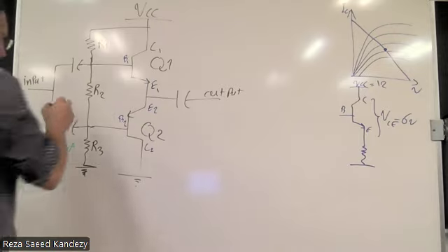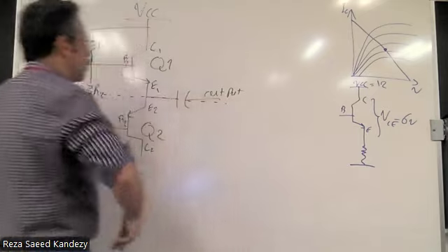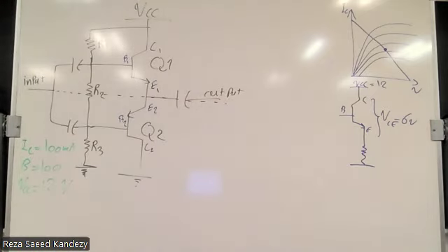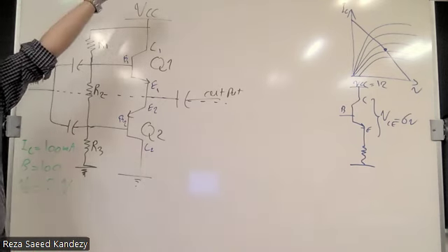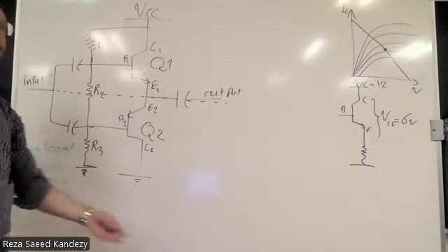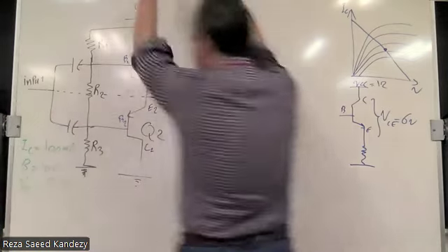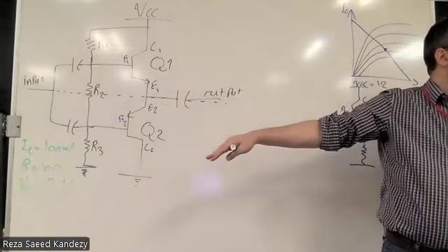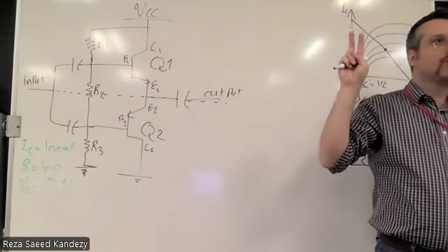That means if we draw the line to cut the circuit in half, half the VCC voltage should happen above the middle line, and half of it should be below it. So, for example, here we have VCC equal to 12. So this half should be 6 volt, this half should be, again, 6. Are we good? This is like a rule of thumb, okay?